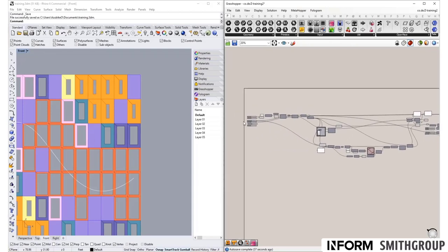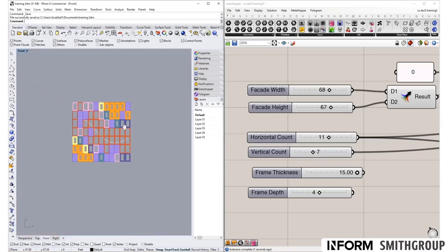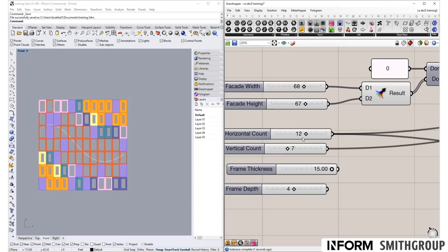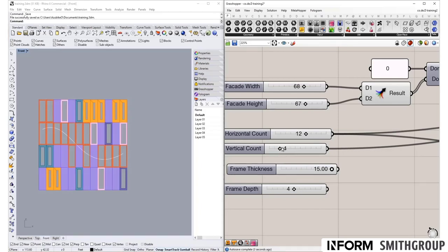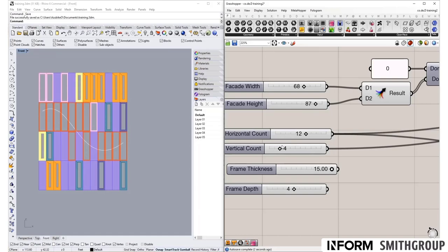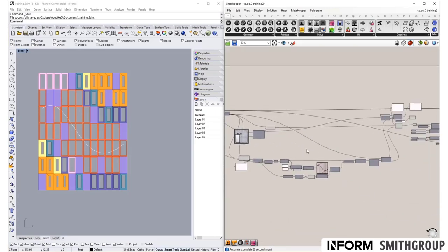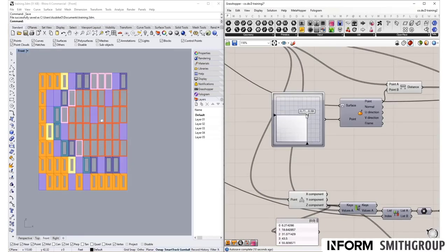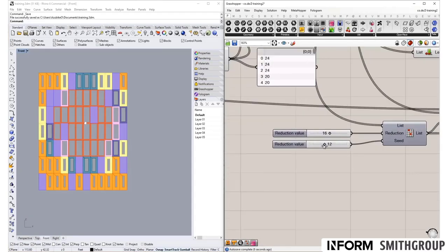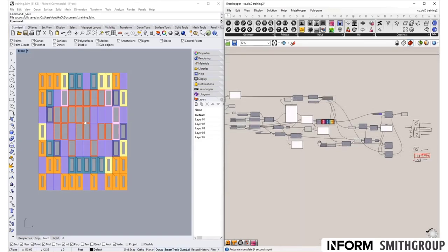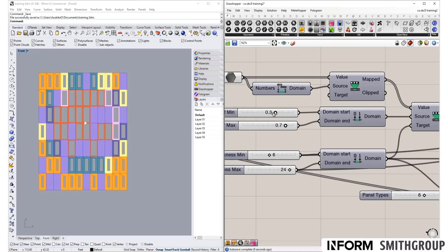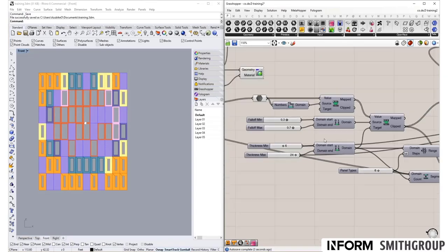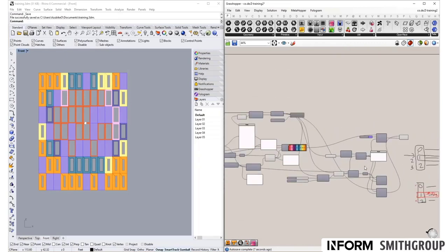And that brings us to the end of volume 1. Modify this, okay, change the count, increase the height, you can do all of this stuff, swap points, control it with the MD slider, increase the number of random panels removed, okay, the fall off, this is how we take advantage of lists and domains in order to operate on lists.